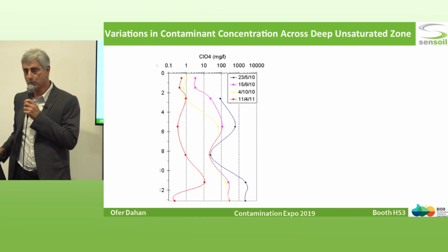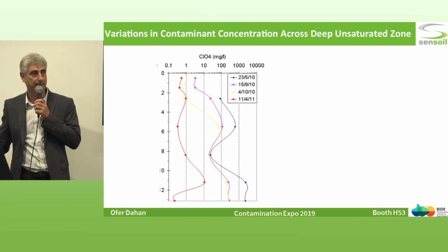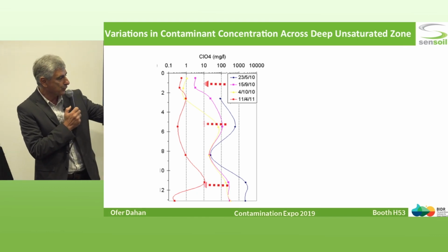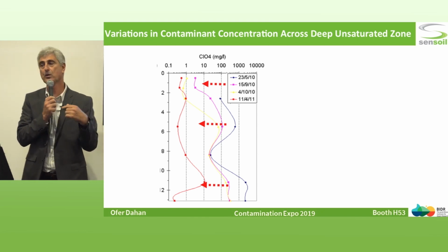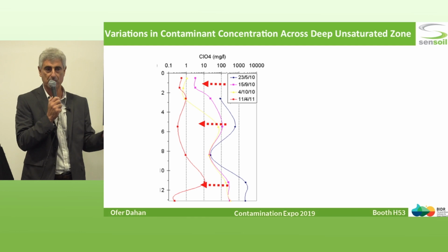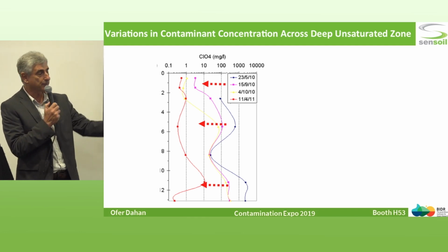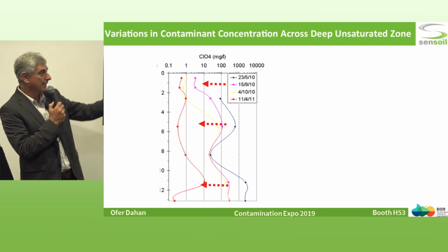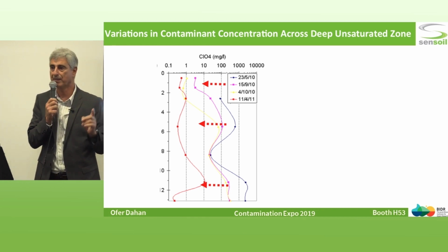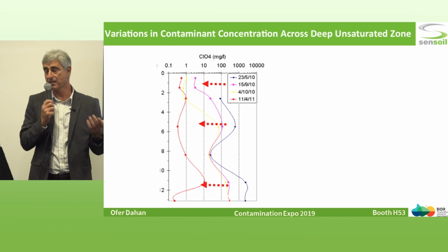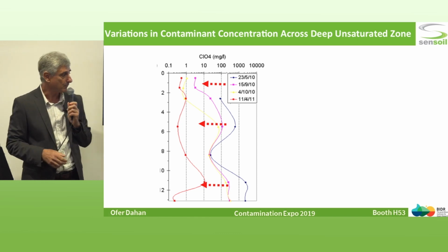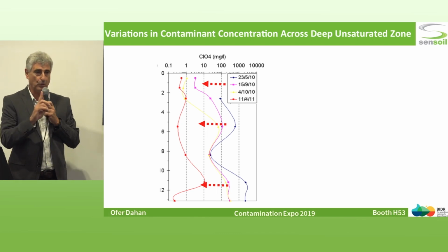But then immediately as we start with the infiltration of the amended water, we see concentrations start to drop down to practically zero. So if you're a consulting company or the remediator, this is the payday. Because you can prove that by that time, you cleaned the unsaturated zone without the need to bring another drilling rig or excavator to see what's going on. You see this in real time and online.